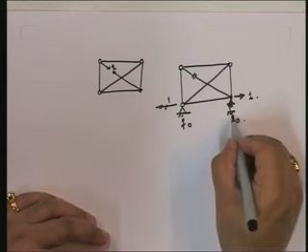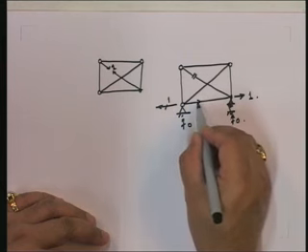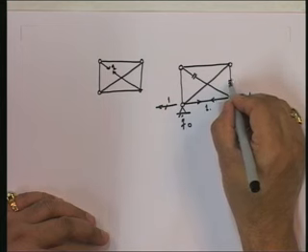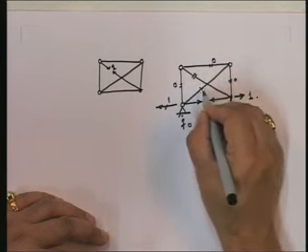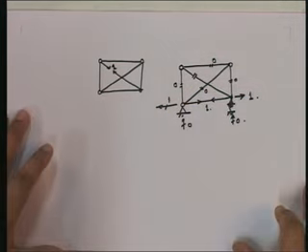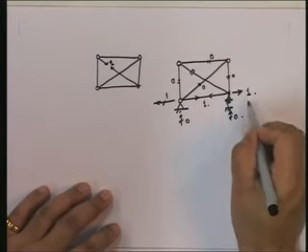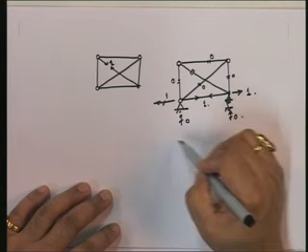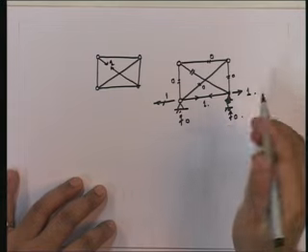That means that due to this displacement, all that we have is a unit force in this member, and all others are 0. So this is the virtual force that I am applying here, and I am finding out the virtual forces in all the members and the virtual support reactions that we have.